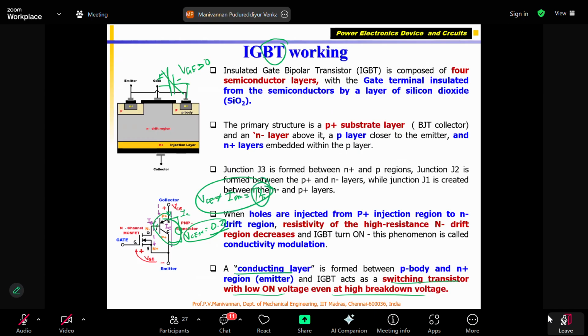Yesterday I told you the power dissipated across the IGBT, transistor, or MOSFET should be 0. All power should be dissipated across the load. But between the collector and emitter, or between drain and source of a MOSFET, or between the collector and emitter of the power transistor or IGBT, there is a voltage drop.